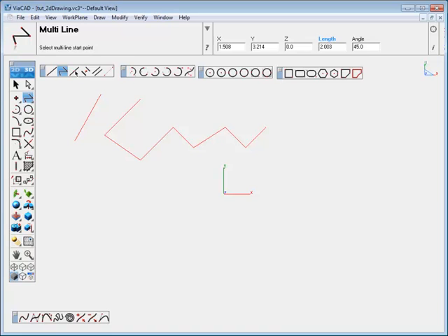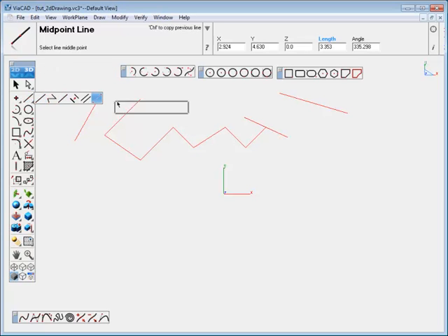The midpoint line allows you to set or draw a line by defining where the midpoint for that line will be and one of the endpoints. The other endpoint is set the same distance away on the opposite side of the midpoint. Drag through the tool set, tear it off, and drop it anywhere in the workspace to give you quick access to the entire set of tools.